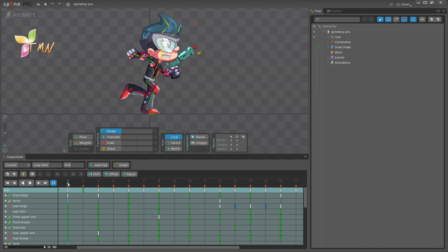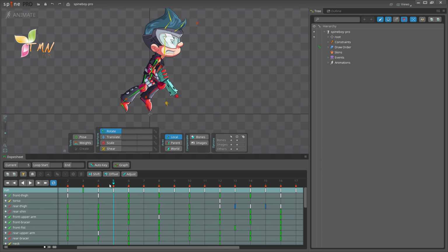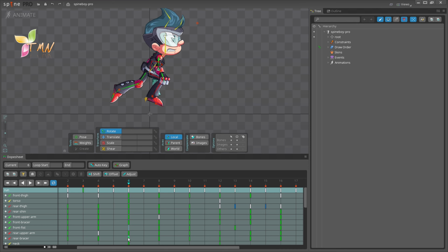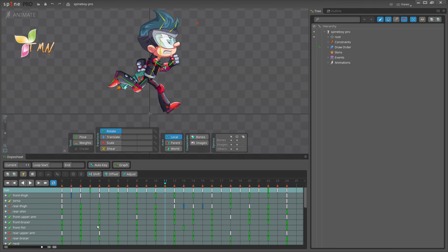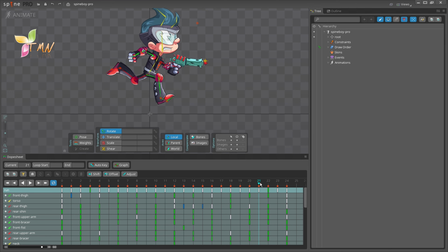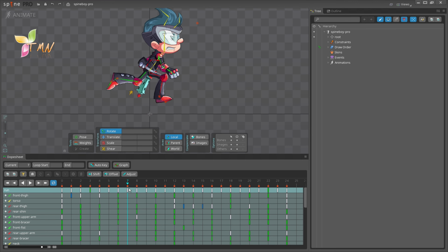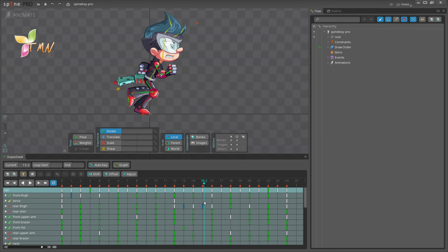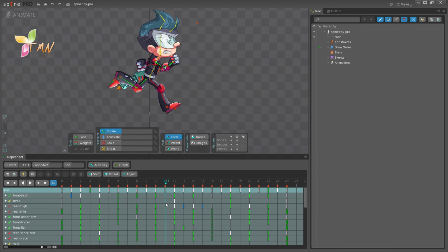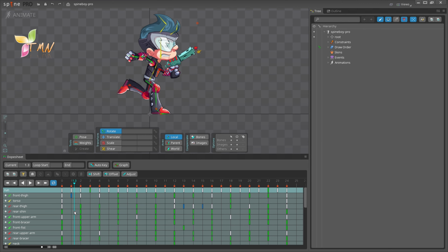The current timeline position is indicated by the line and downward-facing triangle. A new timeline position may be set by left-clicking or dragging. Dragging in the timeline is called scrubbing, and is a quick way to see how the skeleton pose changes over time. Hold Shift while clicking or dragging to set the timeline position between frames. This is especially useful while scrubbing to see the animation interpolate smoothly.